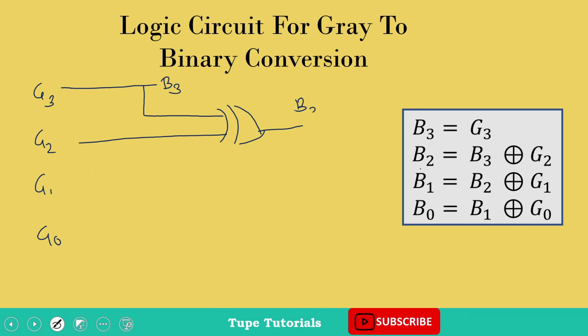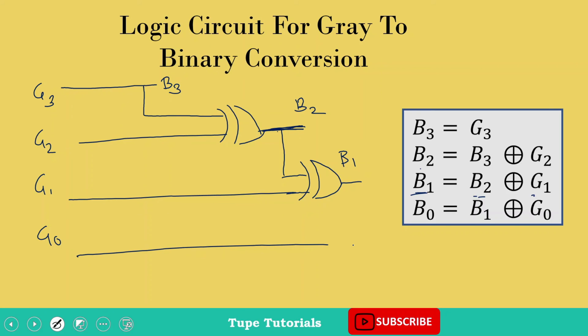Then I will get B2. Now for B1 I will need B2 and G1. So this is G1, and this output B2, I will take it again, and this is my B1. For B0 we will require G0 and B1, XOR it, we will get B0.